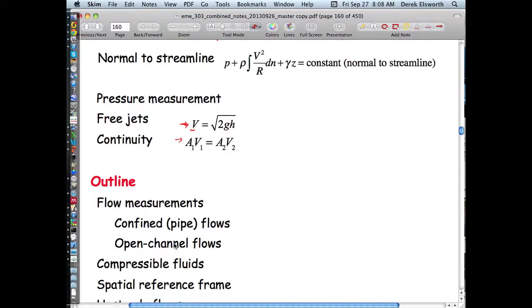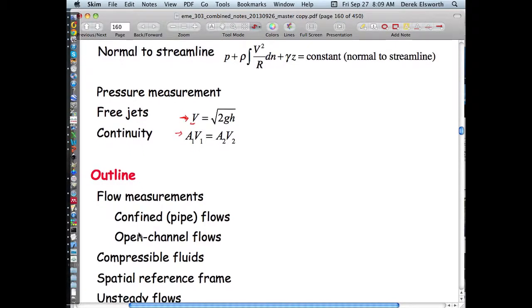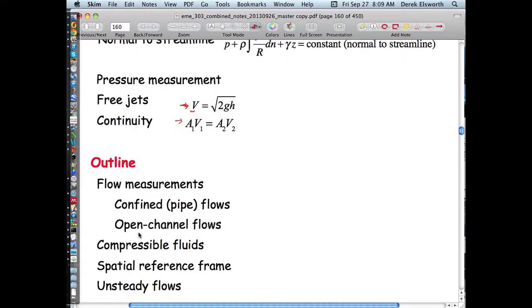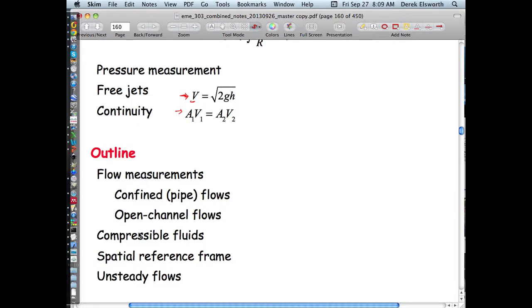And so we started last time to talk about one of the ways in which we've used Bernoulli's law, and that is to be able to define flow velocities. We applied it earlier on to a pitot tube for aircraft, of course, which is an ultimate application of this. But a much more mundane application is to apply it in pipes, where you can measure pressures quite easily and use those to calculate velocities. And so robust measurements of pressures are easy.